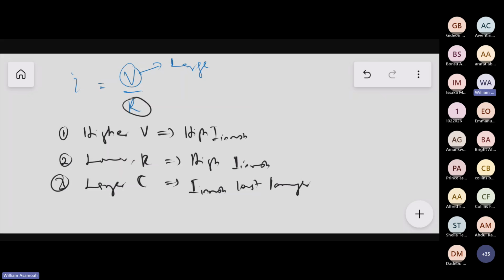And inrush current is a very huge problem in industry, because of variable frequency drives that you use to regulate the speed of a conveyor belt, DC bus capacitors and servo drives, switch mode power supplies. All the power supplies that we use are switch mode power supplies. All of them use capacitors.